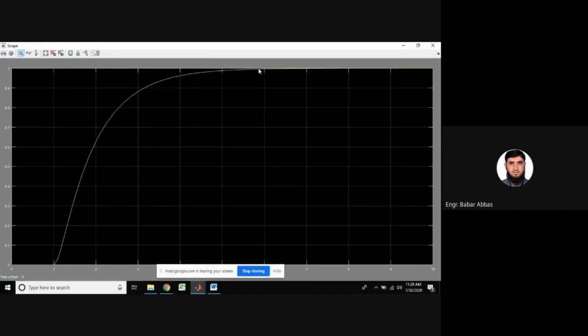And if you people can solve it, there is an exponential to the power minus some value, and that decays. You know that if there is a pole on the negative side of the real axis, exponential to the power minus, then it decays quickly. And our transient response will be a smooth response.